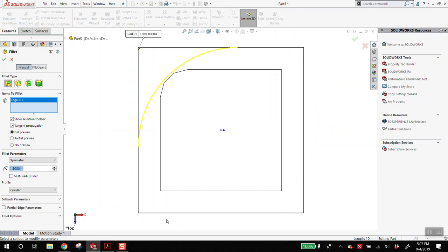Because of that, when you think of your Jenga tower, you want fillets at the top of your tower, but again, it's upside down, because you're building down. You want fillets at the bottom of your tree. Because they fail, you don't want features to rely on them. The other way to think about a fillet is that a fillet is not a design feature, it's a finishing feature. That's a very important distinction.